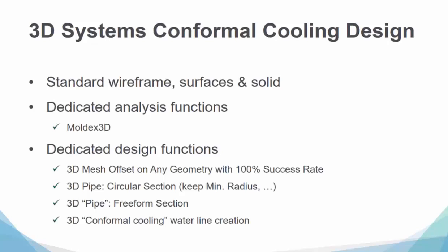We also needed a dedicated tool to analyze it to make sure the flow was what we thought it would be and the results would be what we needed in mind. So that meant some dedicated design functions, which we can't stress the importance of. Being able to 3D offset surfaces without the faces corrupting and falling apart, without all the work of going in there, needlessly trimming or replacing faces, a good offset, whether a shell, whatever command that is, that's within the CAD system is important.